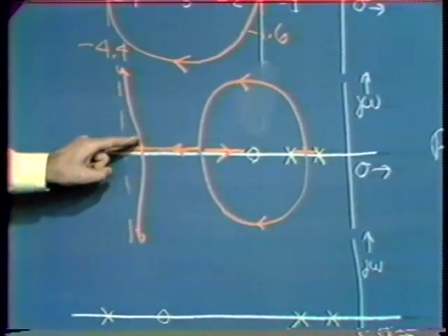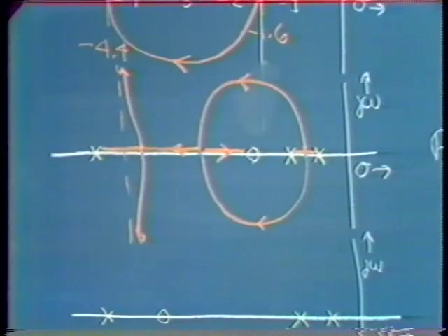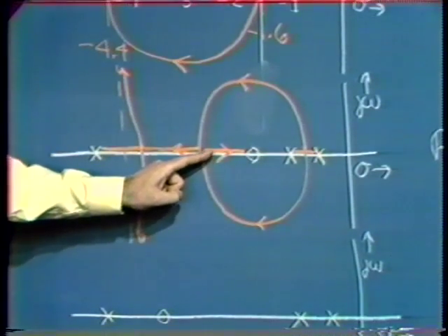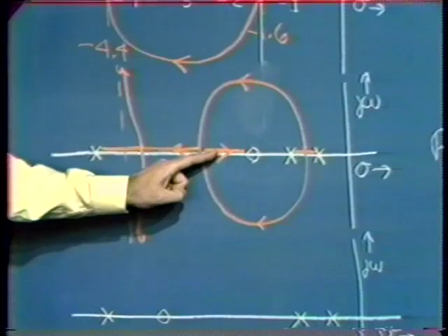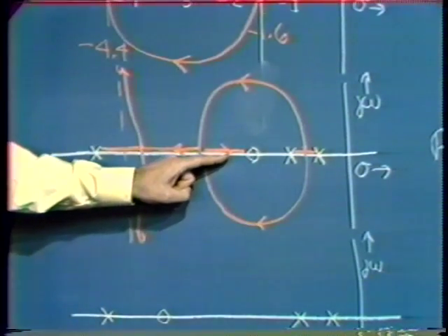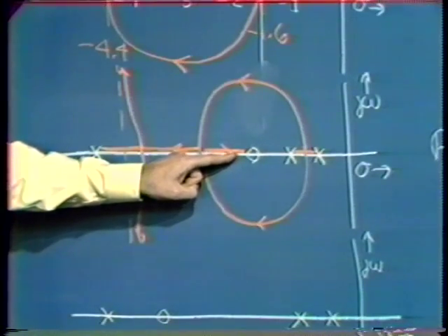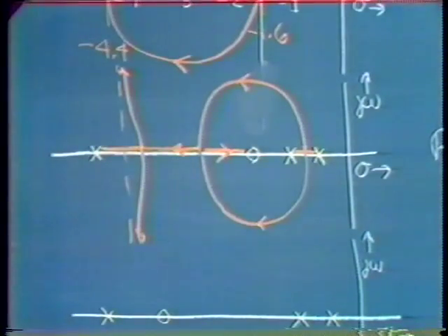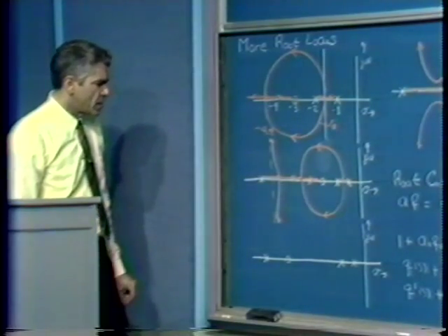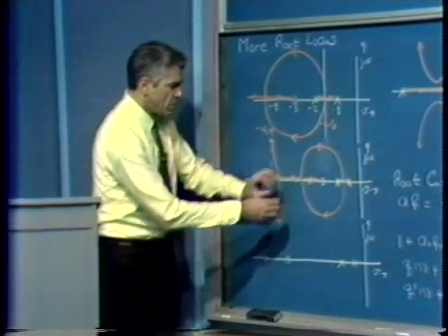The reason for this pair of branches moving away is really, or we can argue that reason by considering the average distance rule. Here we notice that as we increase A naught, F naught, this branch is still moving to the right. Consequently, in order to keep the average distance of the branches from the imaginary axis fixed, these two branches have to move somewhat to the left. Once again, if we had exact numbers for all of these things, we could do a more precise calculation. But at least we see the general behavior.